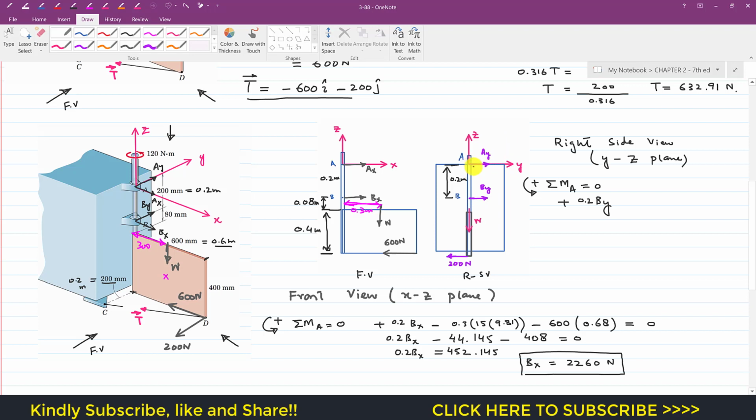Ay is passing through this point A, so it's not going to produce the moment about that point A. So this 200 Newton force is producing the clockwise moment, right? So we will write minus, this is the component of that tension T. This is 200, and again the perpendicular distance of this 200 Newton force from that point A is this 400 plus 80 plus 200, so this is 680 mm, or we can say that this is 0.68 meters, and this will be equal to 0.